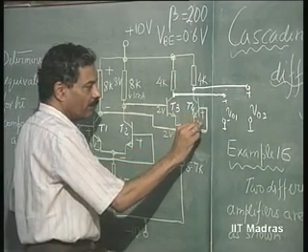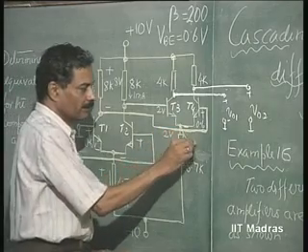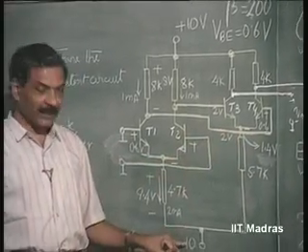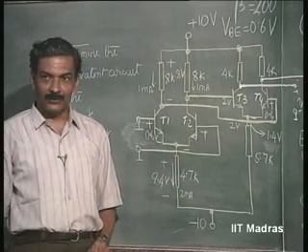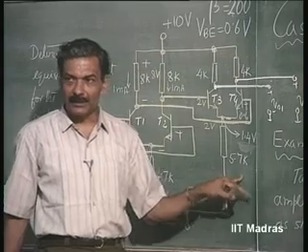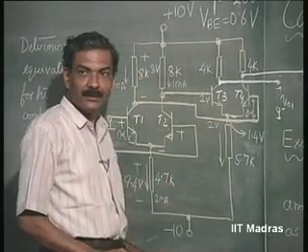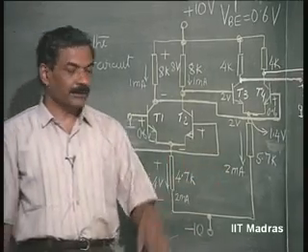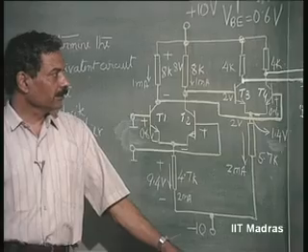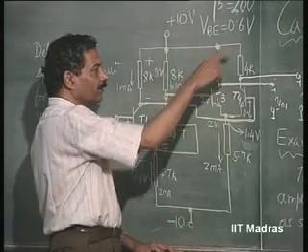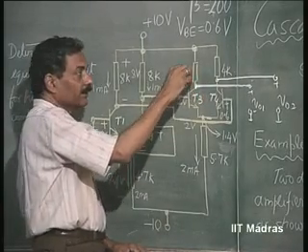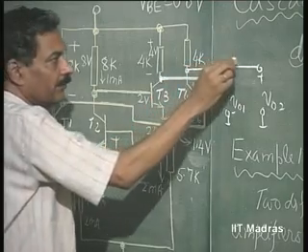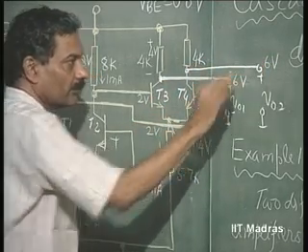Again we have a drop of 0.6 here. So, the voltage here is 1.4 volts. So, once again 1.4 volts, this is minus 10. So, the total voltage is 11.4 volts, and I am fixing the resistance as 5.7 K, which is going to give us again current through this as 2 milliamperes. So, I have purposely fixed these currents uniformly as 2 milliamperes. You can see here the drop across this will be, this being 1 milliampere each once again, 4 volts. So, if this is a 4 volt drop, 10 minus 4, these voltages will be at 6 volts quiescent.